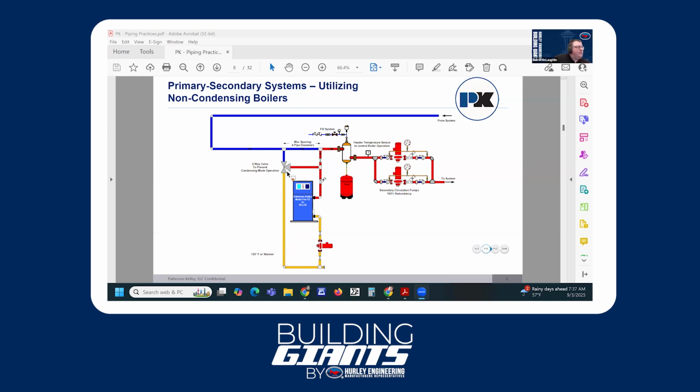If we were to go below that, this three-way valve would begin to stroke, and our outlet water from the boiler would be recirculated back to the return to keep our return water temperatures above 130 degrees. So nothing else in this system has changed. We've still got our standard primary-secondary. We're still pumping away from our point of no pressure change. We're still monitoring our temperature set point here downstream of the outlet of the boiler. But we've just added this three-way valve to protect our return temperatures to make sure that we can operate this without going below temperatures that would damage the equipment.